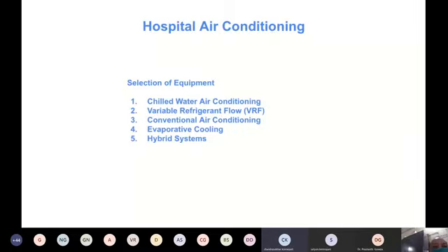We have ductable systems with condensers outdoors and diffusers in the indoor systems. In huge common areas, evaporative cooling systems can be included. And in the last 15-20 years, hybrid systems have evolved in a big way. That means using a combination of the above to reduce both the capital cost and the recurring costs.